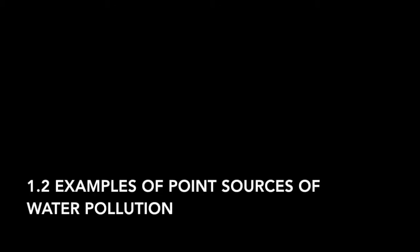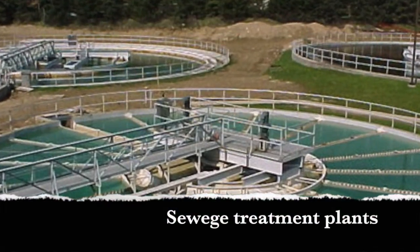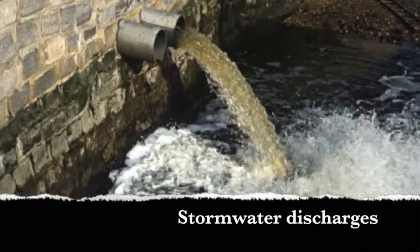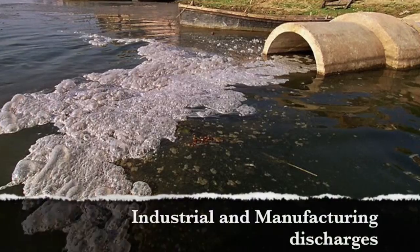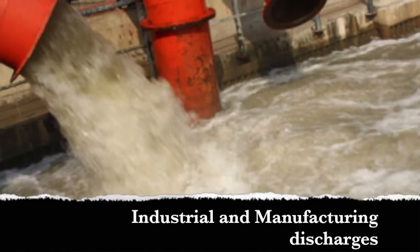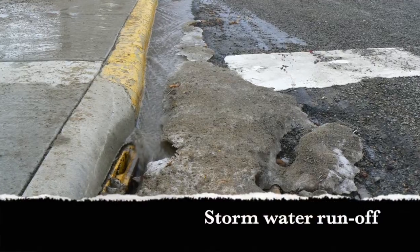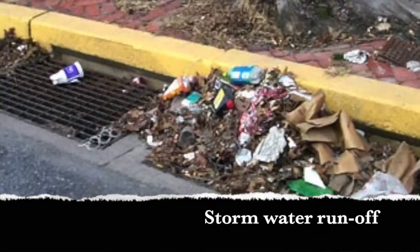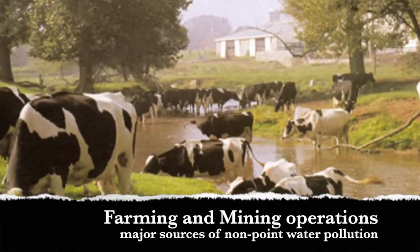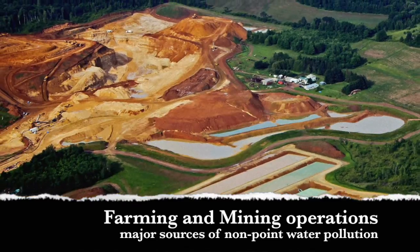Point sources include municipal sewage treatment plants, overflows from combined sanitary and storm sewers, stormwater discharges from municipal and industrial facilities, and waste discharges from industry. Non-point sources include stormwater runoff from hazardous and solid waste sites, runoff from croplands, livestock pens, mining, and manufacturing operations and storage sites.